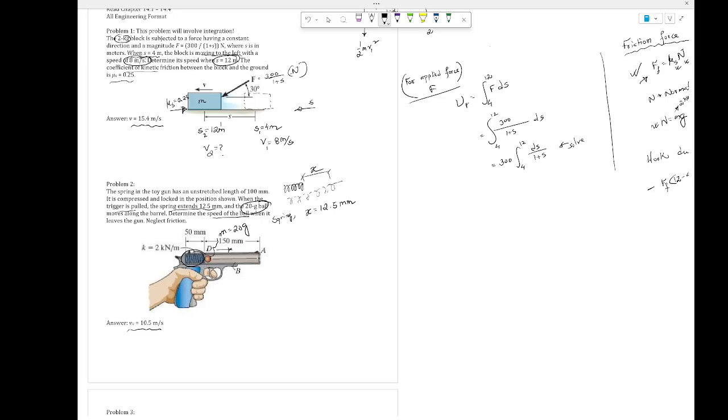Okay. So to solve this problem, to find the velocity, you got to do the first law of thermo or the energy balance. I mean, fancy way of saying first law of thermo, energy balance could be also told here. And the idea is when the spring stretch happens, the spring energy is going to get conveyed to the ball as a kinetic energy, right? When the ball moves, what is the kinetic energy of the ball? Half of mv squared. You know that equation, half of mv squared.